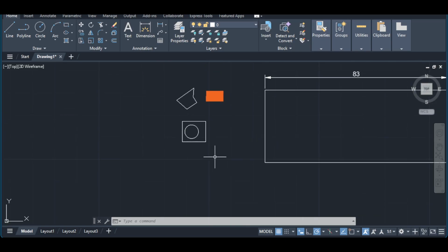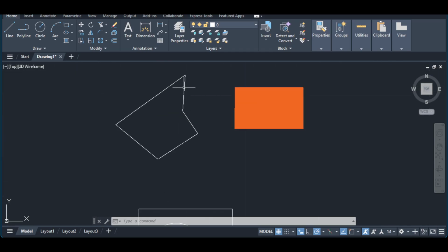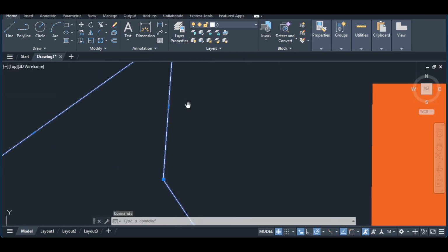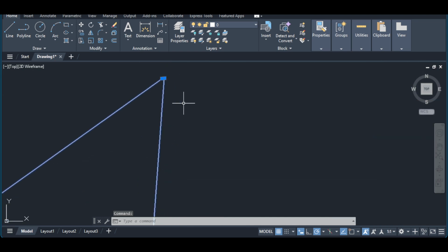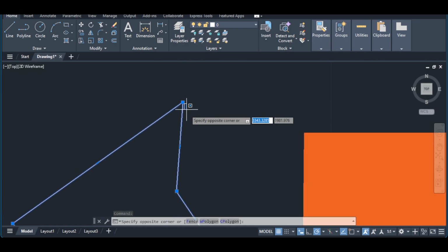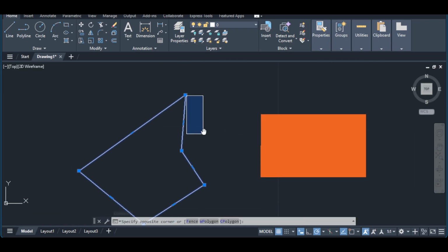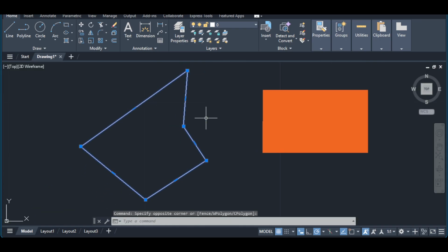Open your drawing and make sure your lines, polylines, and shapes are clean, connected, and organized on the proper layers. If you see broken edges or segments that should be one continuous boundary, use the join command to connect them. For more control on polylines, PEDIT is your friend. It lets you edit polylines and join multiple segments into a single polyline. Zoom in on corners and intersections to catch tiny gaps.